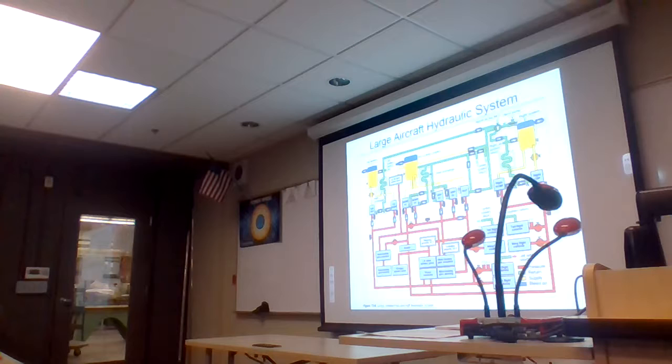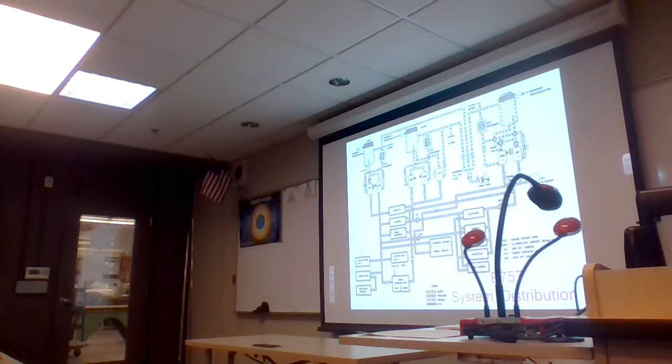So anyway, this is what we look at for kind of a large aircraft for a typical system. And this is one from a 757 aircraft showing the complete system. Again, left, center, and right, and again, simplified. And it shows you that, for example, on spoilers, you've got several different inputs that all provide hydraulic power. And if one system is lost, well, you still can operate spoilers, ailerons, or thrust reversers. And so it works pretty well.